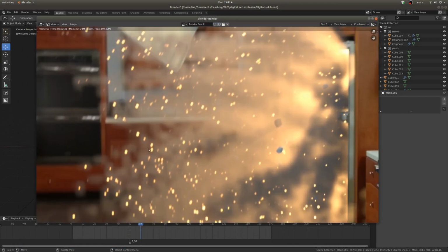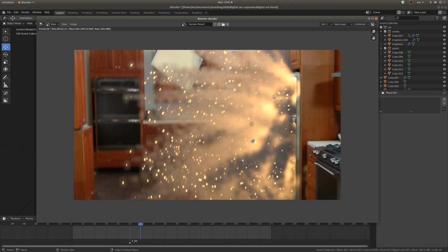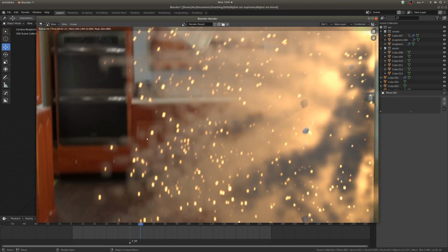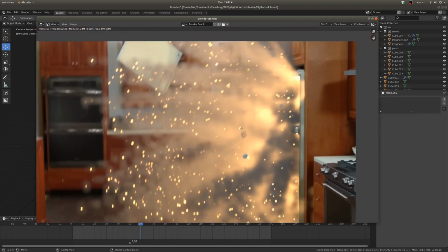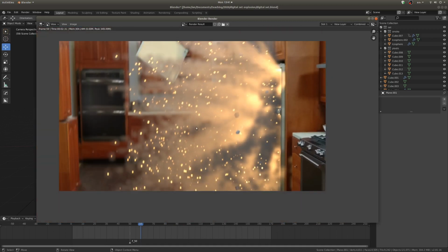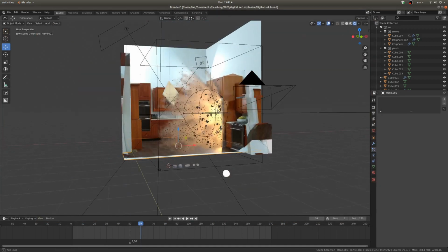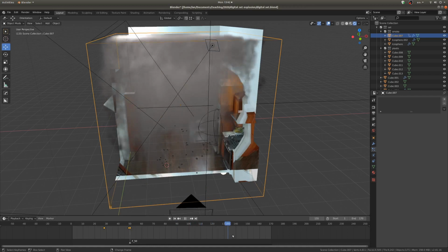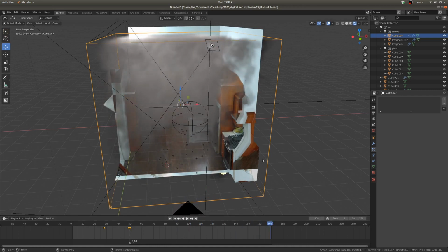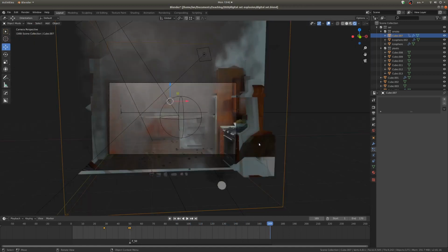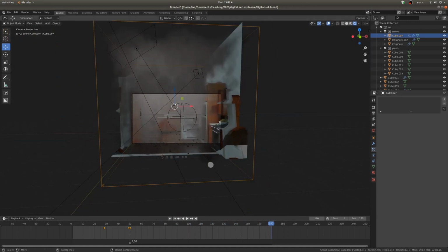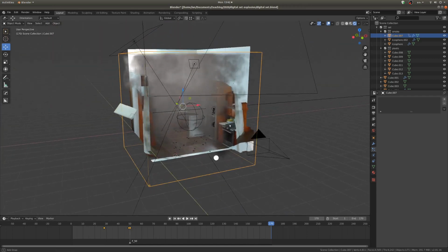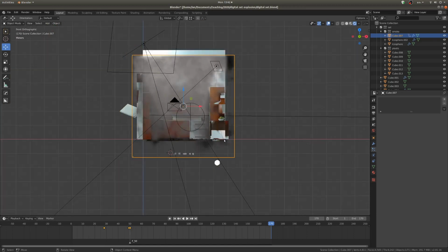it looks fairly good. One thing that I'd like to work just a tiny little bit more on is the resolution of the smoke simulation. You can see we've got some low resolution stuff going on here still, and it just doesn't look as high resolution as I would like. So something I'm going to do a little hack on with that. First of all, let's go to a place where our domain is in full sight towards the end here, and where our camera is as far out as it's going to get. And you can see we've got all this and all this down here, and that's all smoke resolution that's going to waste, and I've baked it, but you just can't see it.